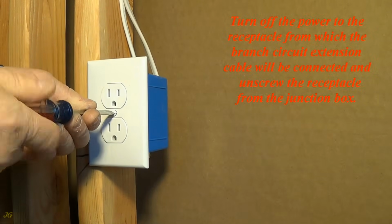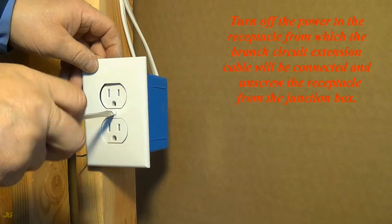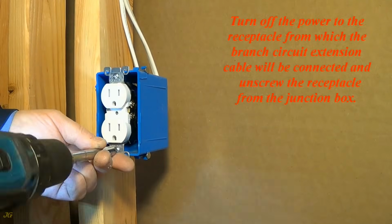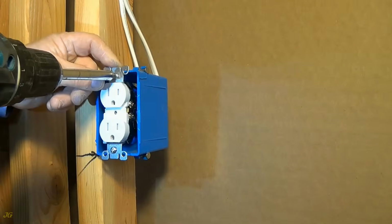Turn off the power to the receptacle from which the branch circuit extension cable will be connected and unscrew the receptacle from the junction box.